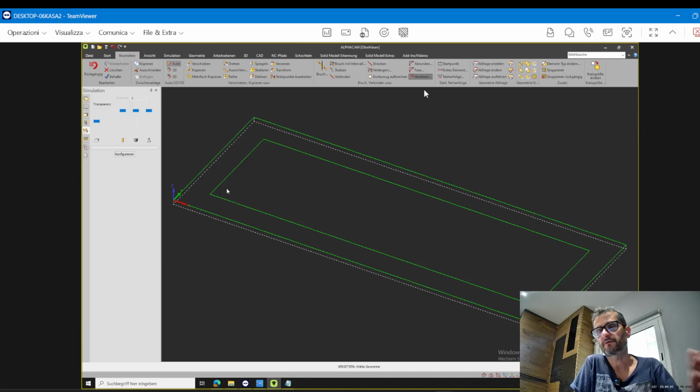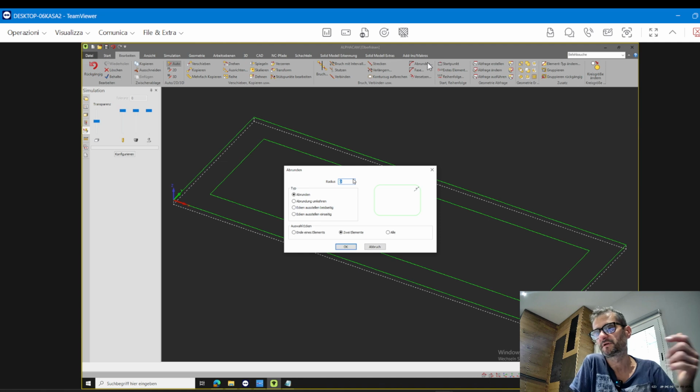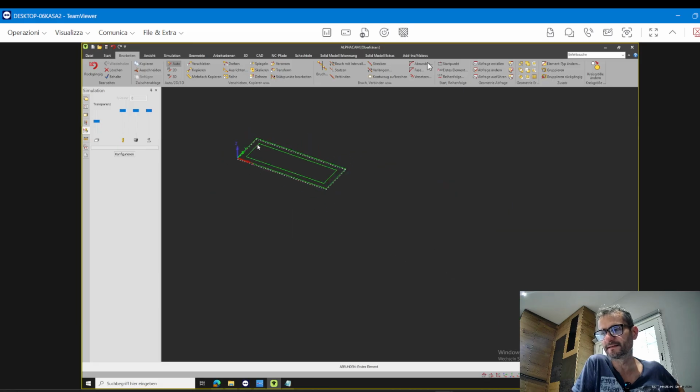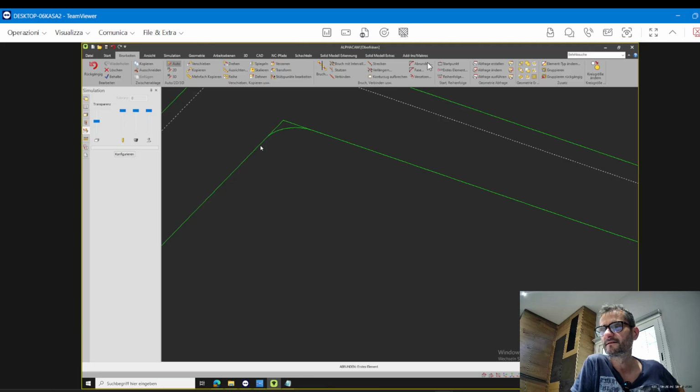For example, like we did before, we make a radius between two corners, between two lines. If we want to make a corner or a radius, you can do something like this. You say the millimeters that you want for the radius, and you pick the two lines. Yes, this side, perfect. And I will explain why a part is not deleted, but it is not a mistake. Do I click enter now? No, it's okay, it's already done.